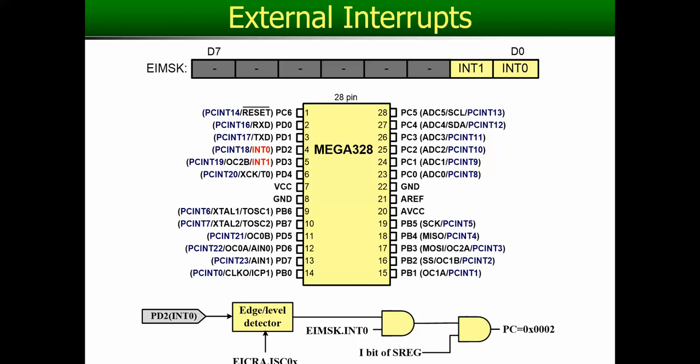Somebody has to help me remember that I was in room number 5 before. So how would we remember that? There is a stack for that. There is a separate piece of memory allocated for that. Whenever you make a jump, the current address of the instruction is stored on the stack. It's pushed onto it, and that all happens in hardware this time.